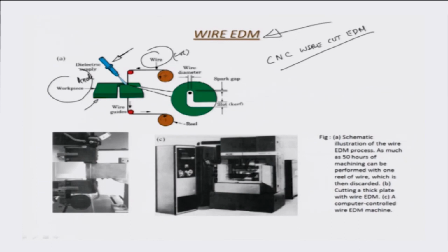So the wire actually is fed from a roll. You can see between this roll here and this roll here, the wire is being fed, and as the wire slowly emanates out, there is a discharge which happens between the wire, the cathode, and the workpiece anode, and wherever the wire moves, so this slot right here is an L slot which is otherwise seen in the top view.